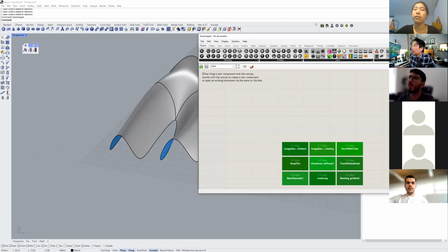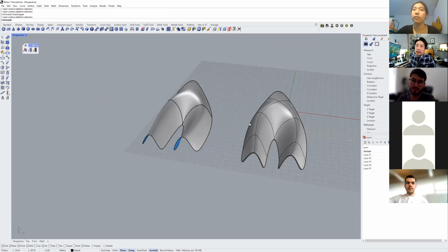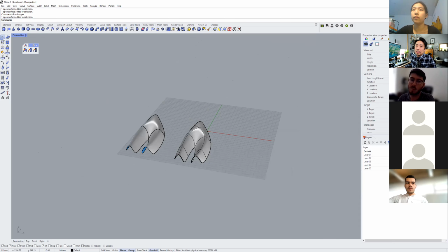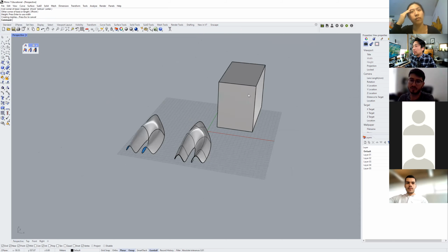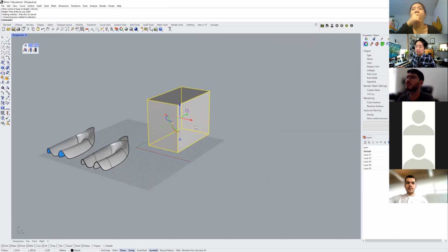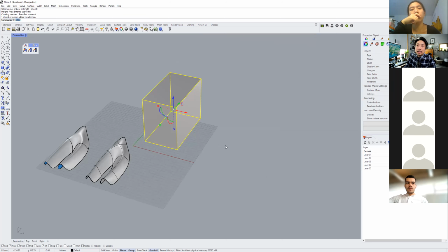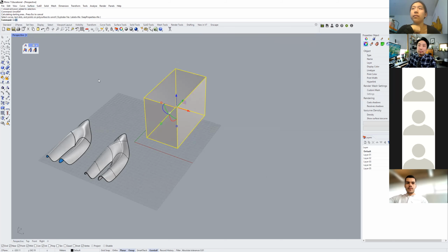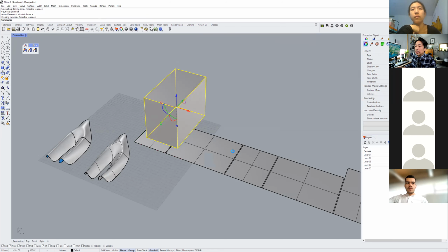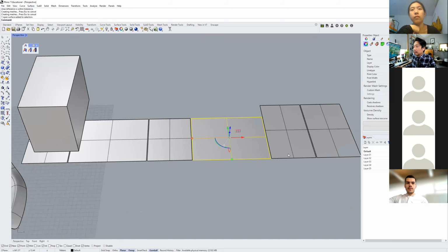Okay. So I want to walk you through this feature that's in Rhino, and it's pretty robust. You can take shapes and unroll it, unfold it, right? So for example, if I just come here, create a box, right? I can just start typing, unroll surface. Okay, right click again, and it will show me how this piece can be unfolded into individual faces.